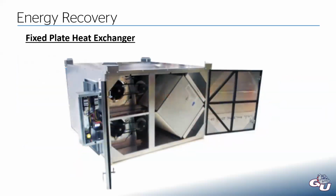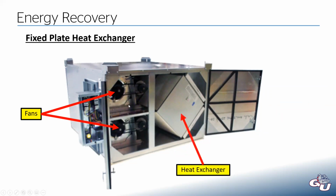And here's one that I spec'd on many jobs, and this shows what it looks like. Actually, if you think back to when we talked about Tico Elementary, I had some photos of one of these out in the wild. But we have our two supply fans. So that's what's moving our air. One would be for the outside airstream, and one would be for the exhaust air. You can see the motor tucked away back there with a belt to drive our fan impeller and the fan casing right there. We have our heat exchanger core there in the center. And you can see we have filters here as well.